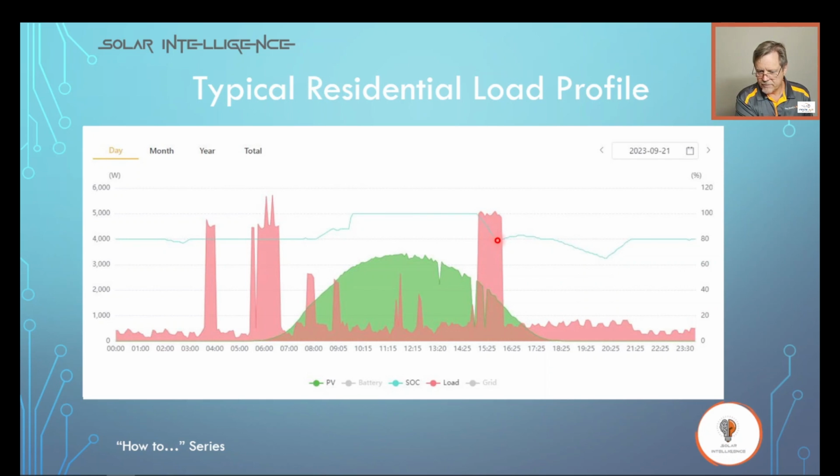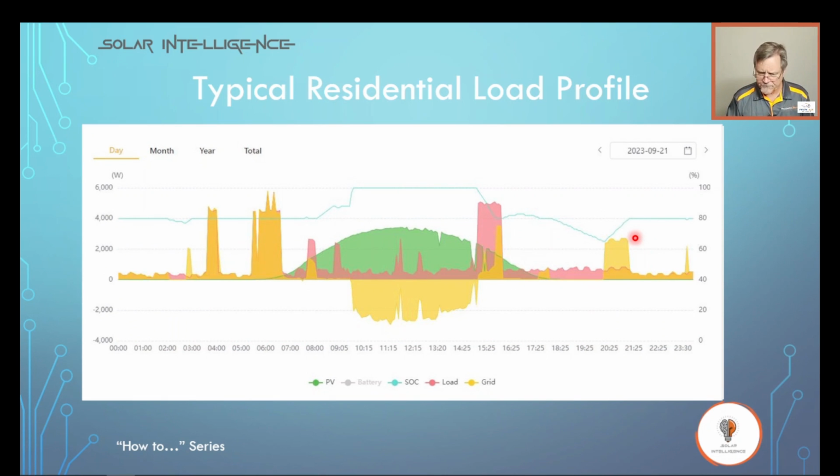It drops up to the point where the battery reaches the pre-configured self-consumption limit, as I mentioned earlier, and at that point, the inverter makes the decision saying, I'm not going to let the battery discharge below 80%, I'm now going to start using the grid, and we'll see just now how that works. And then we start using the grid, the battery later discharges further, and we'll see just now why the battery discharged below 80% and needed to recharge again to 80%. Now let's answer that mystery.